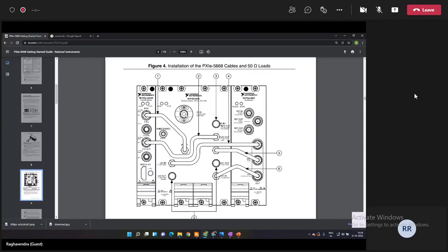So let's say, for example, there is some signal that's supposed to come in at 20 gigahertz. Obviously, our USRPs cannot take in that 20 gigahertz. What we can do is give the signal to this 5606. The down converter is called 5606. You can give it to this.